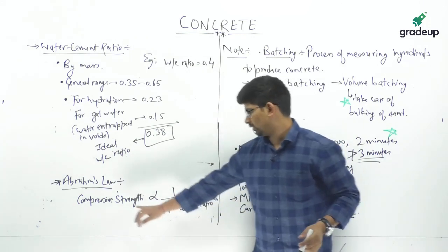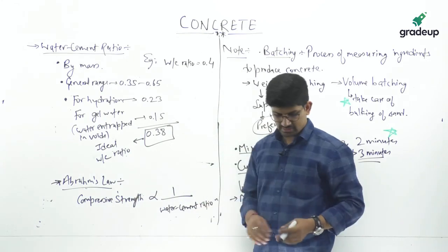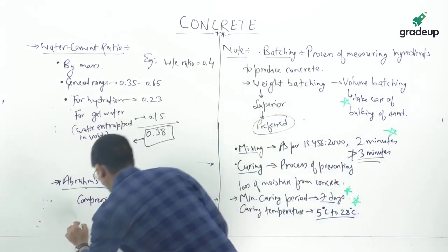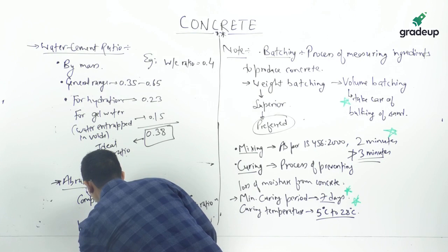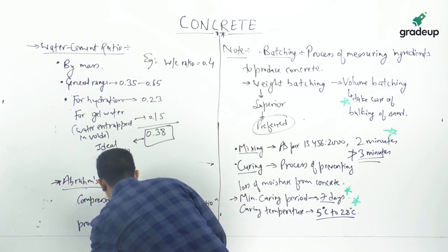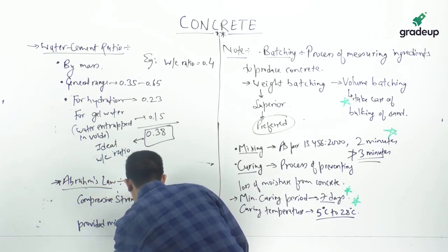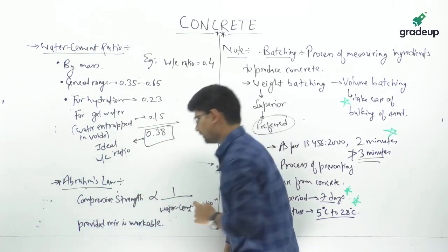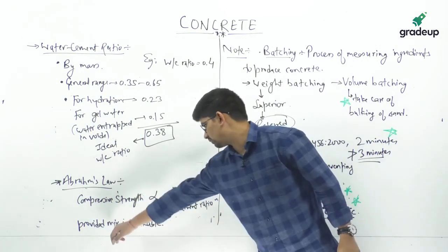Lesser the water cement ratio, more is the compressive strength, but there is a condition, provided the mix is workable.